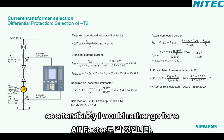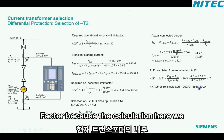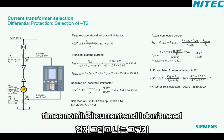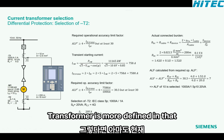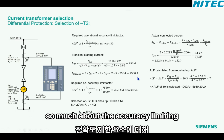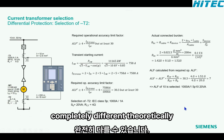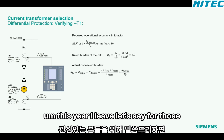As a tendency, I would rather go for a lower burden value and a higher ALF factor, because the calculation here we need to rely on the internal resistance of the current transformer here, this 4 ohm. And if I say I need 30 times nominal current and I don't need so much burden, then maybe the current transformer is more defined in that direction than saying I need the incredibly high burden and I don't care so much about the accuracy limiting factor. But again, as long as these requirements are fulfilled, everything is fine, and the current transformers can be also completely different theoretically.